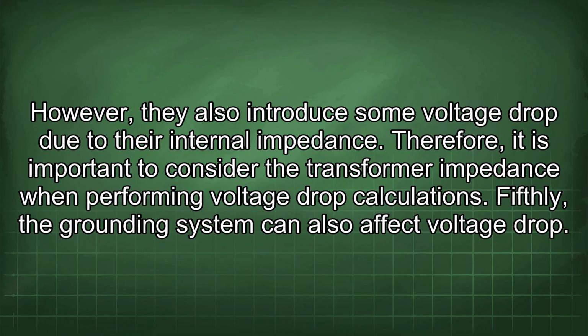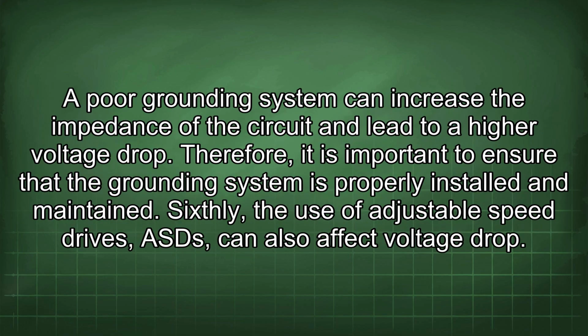Fifthly, the grounding system can also affect voltage drop. A poor grounding system can increase the impedance of the circuit and lead to a higher voltage drop. Therefore, it is important to ensure that the grounding system is properly installed and maintained.